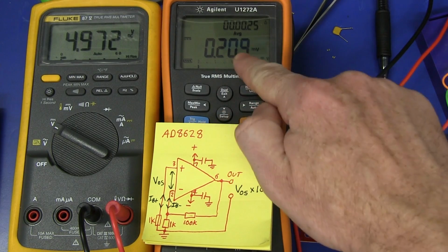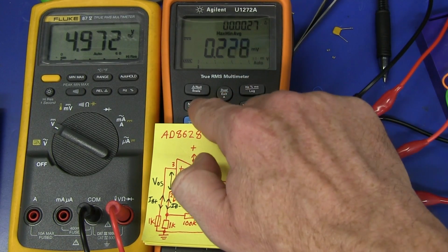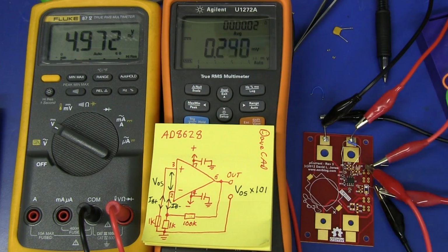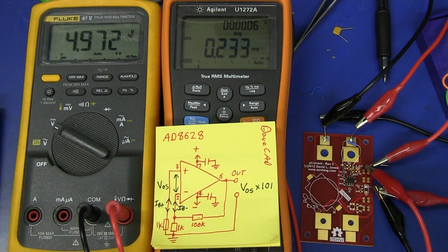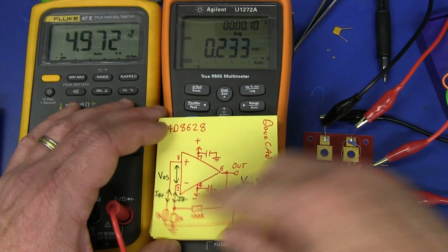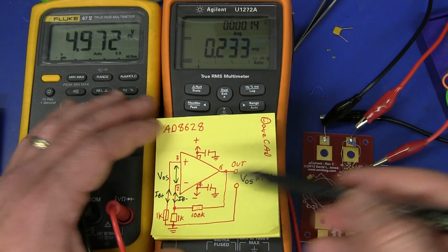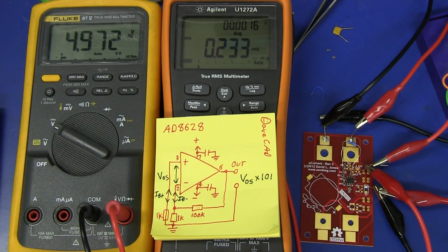Anyway, it's dropped from 300 down to 200. So that is a change, which I would have been surprised if we didn't get any. There we go, it's 240. So it's changed by 70 microamps, but it's still, as you can see, even with the input bias resistor in there, properly designed, it's still not happening.